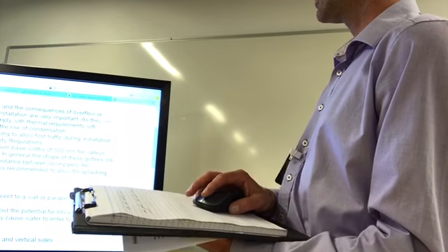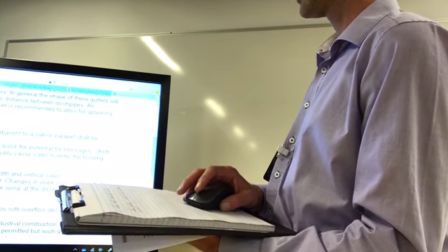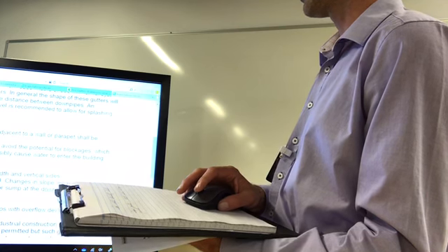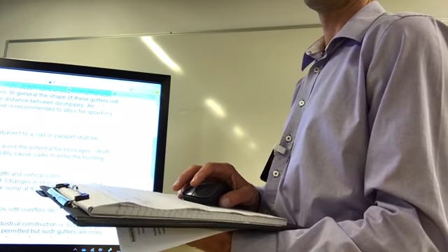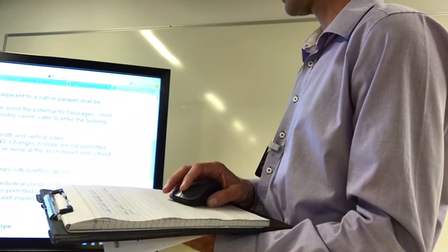So there's this information page on your box gutters, and longitudinal slope must be between 1 in 200 and 1 in 40. We went for our minimum slope.